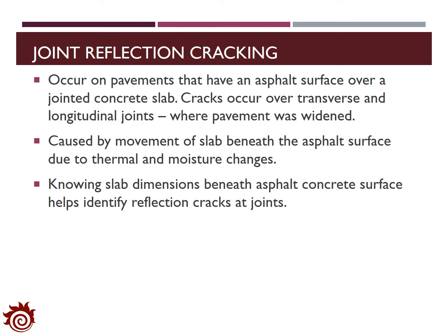The next one is joint reflection cracking. This one usually occurs on pavements where the asphalt surface is overlaid on a jointed concrete slab. This crack usually occurs over transverse and longitudinal joints where the pavement was widened.